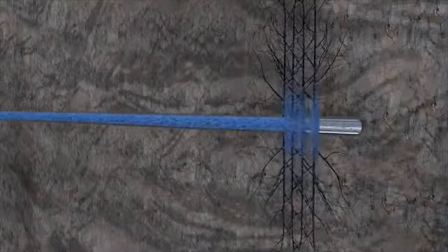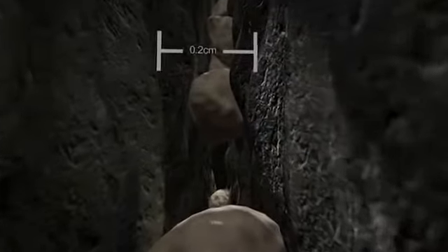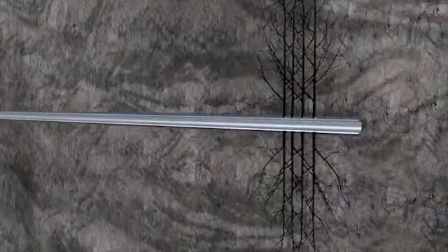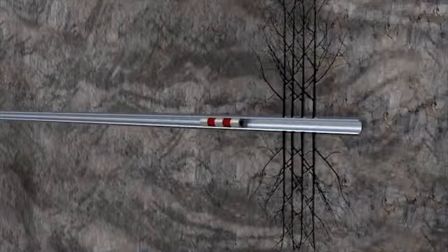The sand in the frac fluid remains in these fractures in the rock and keeps them open when the pump pressure is relieved. This allows the previously trapped oil or natural gas to flow to the wellbore more easily. This initial stimulation segment is then isolated with a specially designed plug, and the perforating guns are used to perforate the next stage.